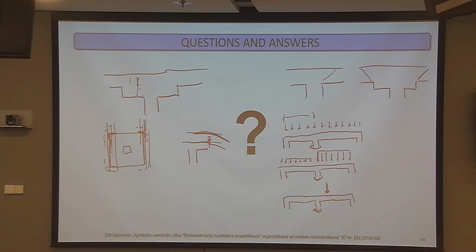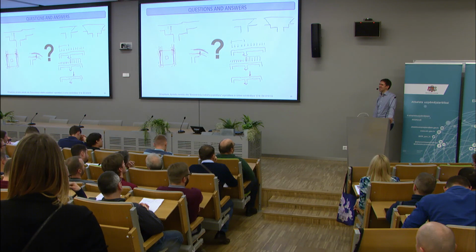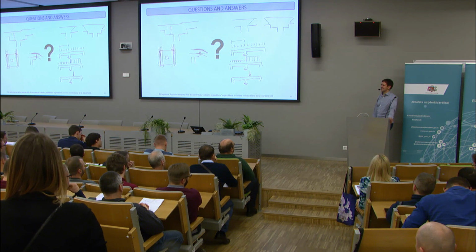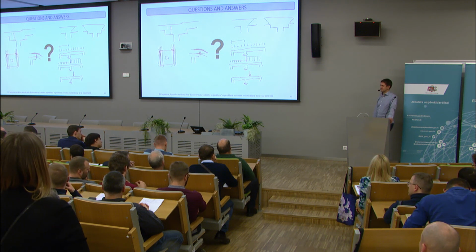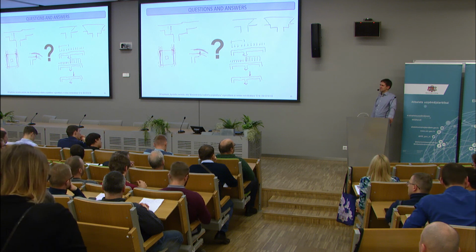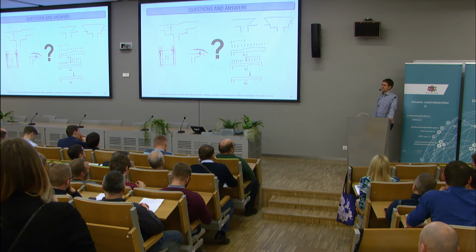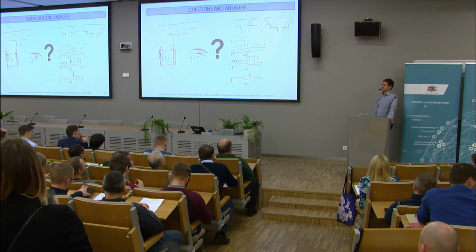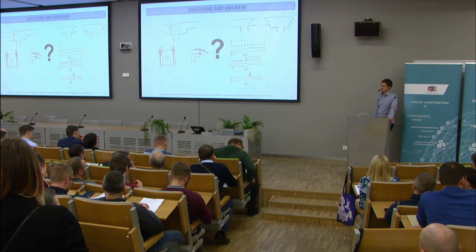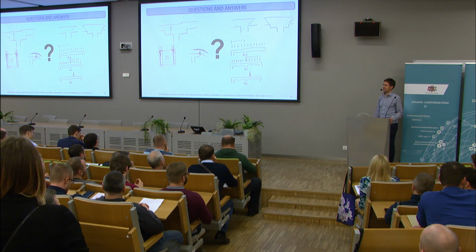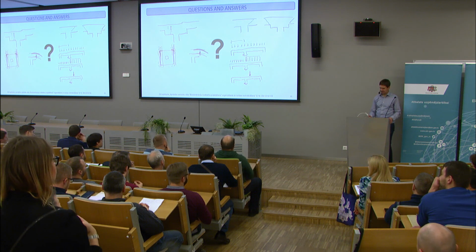The question about this was actually, in these cases, do you need to, for example, find tributary areas for shear force transfer and use them in conjunction, like find the tributary area aside of a column which has the highest nominal shear flow through it, and use it in conjunction with beta, which is higher than 1, to find the maximum shear stress in that zone of the perimeter?